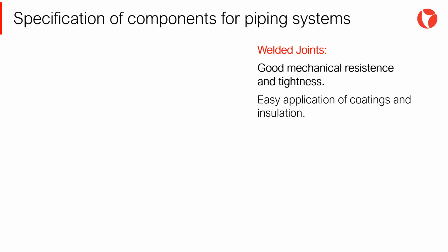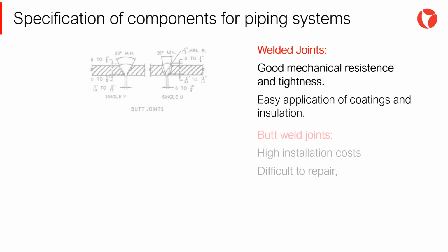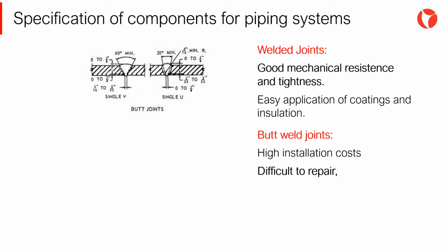Welded joints present good mechanical strength, the preferred option over threaded joints, especially for applications with considerable pressure and temperature requirements. Within the welded joint configuration, the following can be found: butt welded joints. This type of joint configuration presents the highest mechanical strength of all methods, being the most costly of all alternatives except for the flanged joint application.